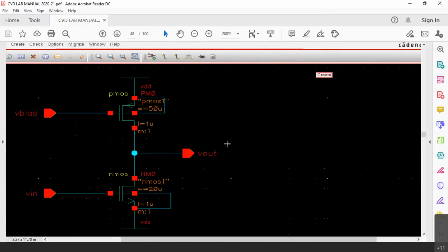Now instead of the resistor, you are seeing a transistor at the top. And below you are seeing the regular amplifier transistor. This N MOSFET is basically an amplifier transistor where you have input and at the drain there is output. Input is given at the gate. What difference do you see when you compare this circuit with the circuit which I had written earlier? One difference obviously is the resistor is replaced with the PMOS.